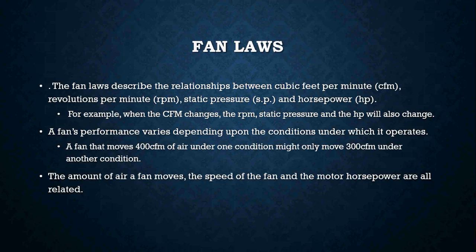Because what it does, it describes the relationship between a couple of things: your cubic feet per minute, or CFMs, revolutions per minute, which is your RPMs, your static pressure, and horsepower.